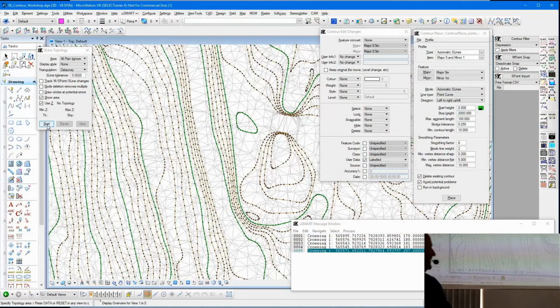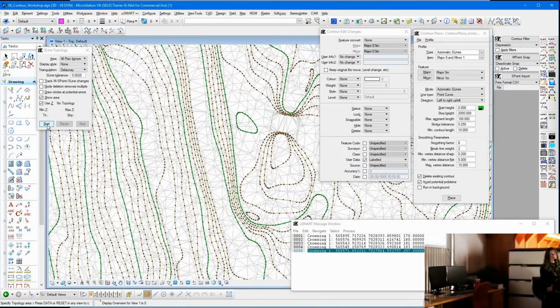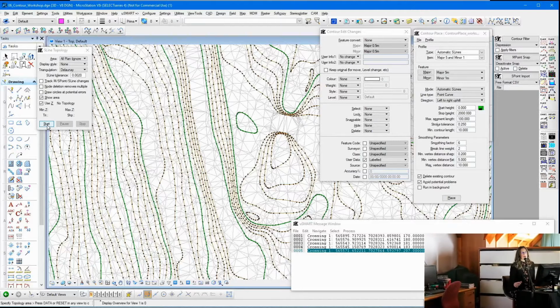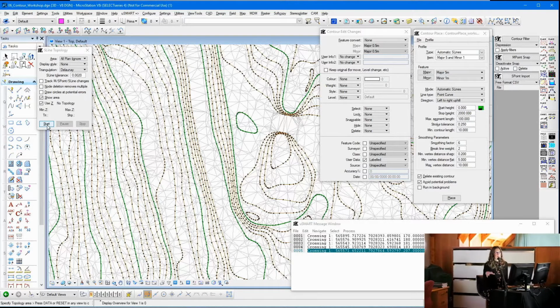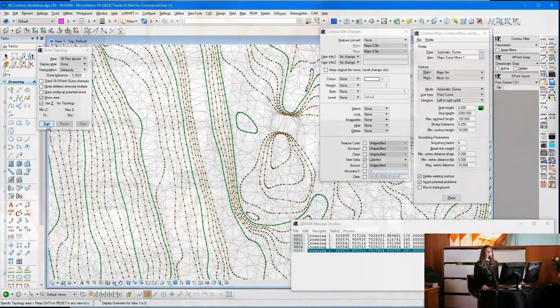Say we take the point cloud and we run the contours in uSMART. Now then a month later we have a spike in the data. And we regenerate the contours. What happens to the edits? Just want to say that you don't have to rerun all the contours. So if you edited that area where you found the spike, you don't necessarily have to rerun all the contours.